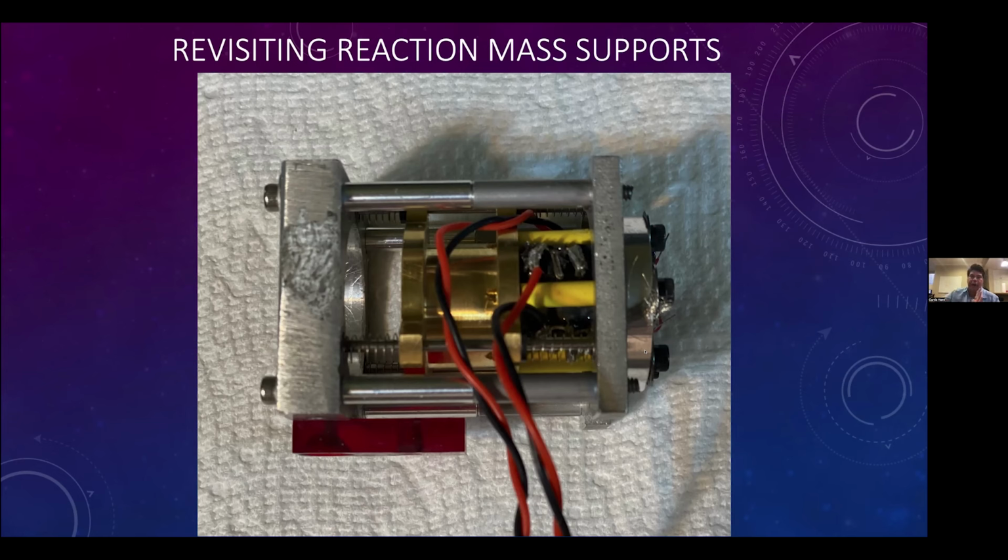So if we spread out the bearings, that should help with the stick slip issues that we're getting. So we're taking steps to test that. We're going to be testing this device again, and I'm hoping to get an aluminum cap with ears with supports so that we can put supports on the furthest points away, and see if that helps us out.